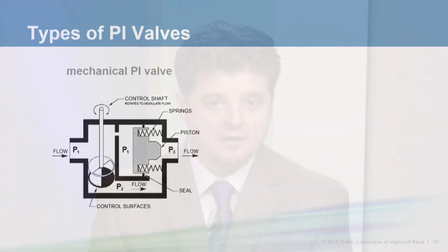Stability and accuracy are particularly important. Anything that causes the valve to lose accurate and stable flow control under any operating condition will result in lower than desired average waterside delta T. Of course, lower delta T can result in a dramatic increase in pump power and a decrease in chiller plant efficiency. So how do pressure-independent control valves work?